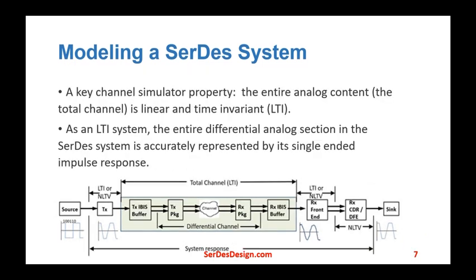A key assumption to the channel simulator to keep in mind is that it considers that the entire analog content, the green area in this figure, the total channel between the transmit AMI portion and the receive AMI portion, is linear and time invariant. As an LTI system, the entire differential analog section in the SerDes system is accurately represented by its single-ended impulse response. The key concept enables this channel simulator to achieve its fast simulation speeds.